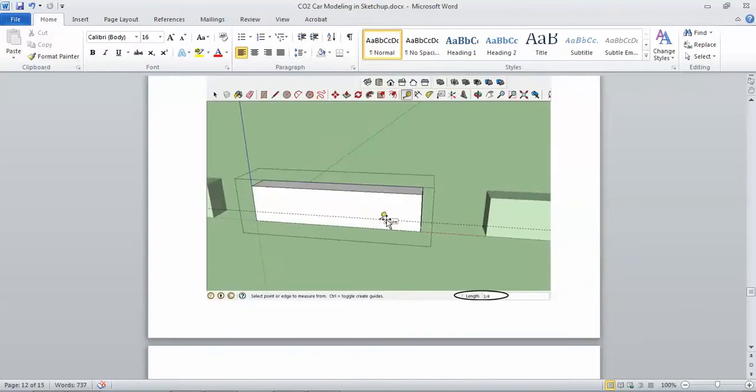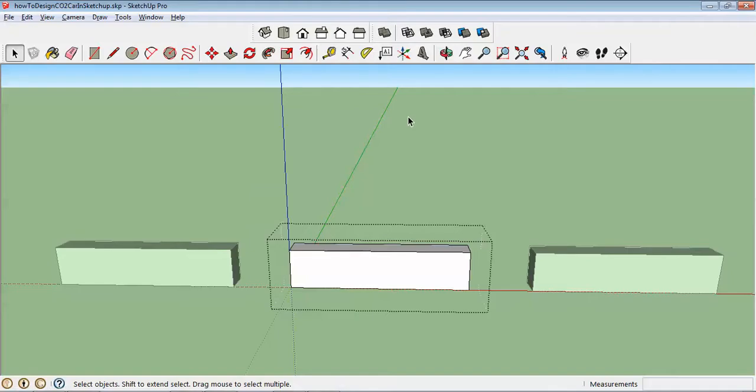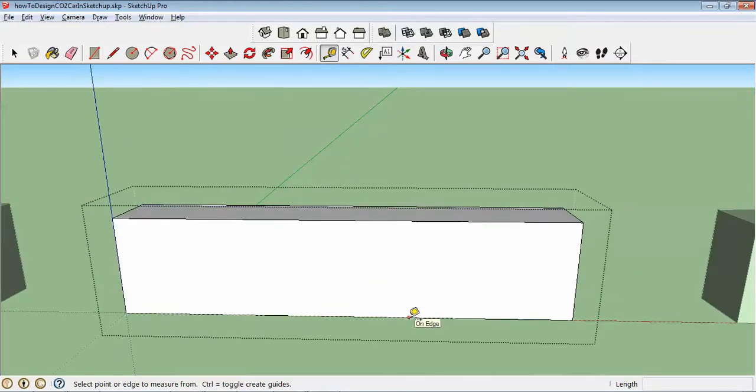So basically, we're going to use that tape measure tool again. Grab the tape measure tool. I'm going to zoom in. I'm going to click down here at the bottom, and it starts pulling up a dotted line, just like the dotted line we just barely created. And I'm going to type in 3/4, enter. You see that what I typed ended up in the bottom right-hand corner, but this is not a text input box that you can click on. Do not click right here. That'll ruin it. Let me undo and redo this step.